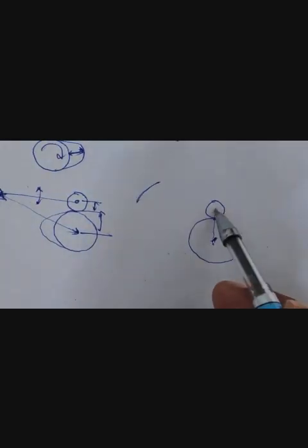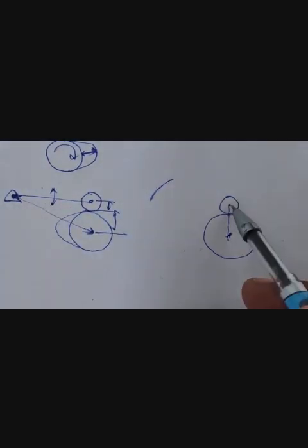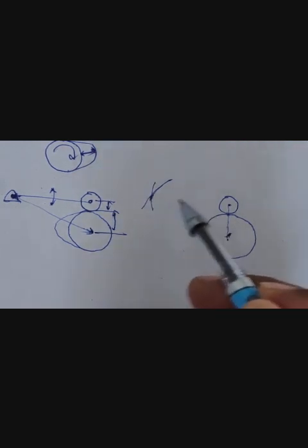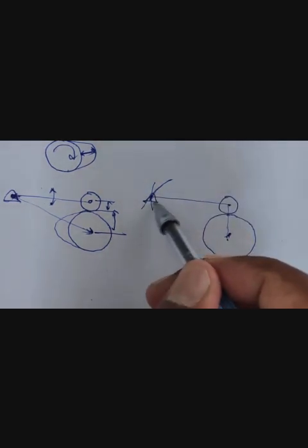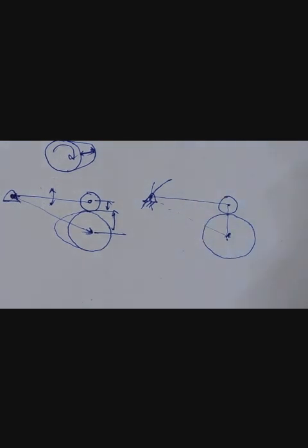And again you know the lever length here, so from this point you cut an arc like this. These two arcs cut here. So this is the pivot for the lever, and this is the distance. This is how you start a problem in the case of an oscillating follower.